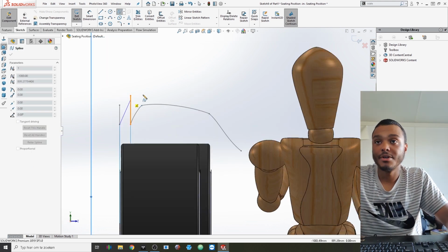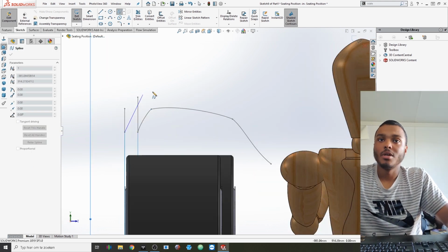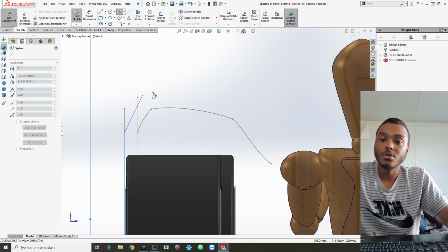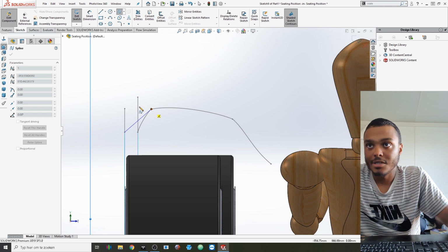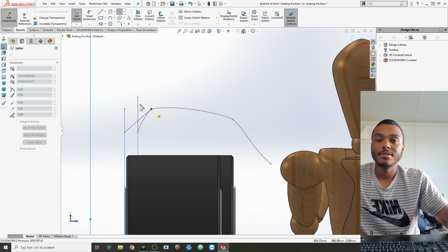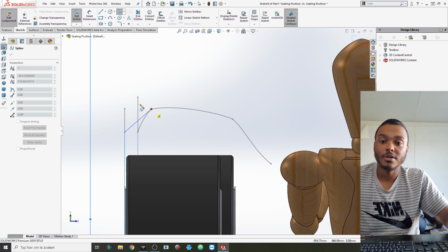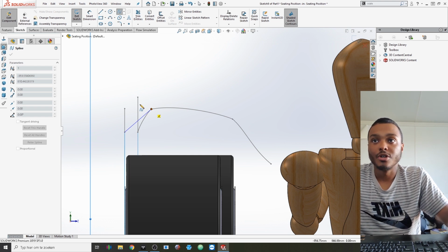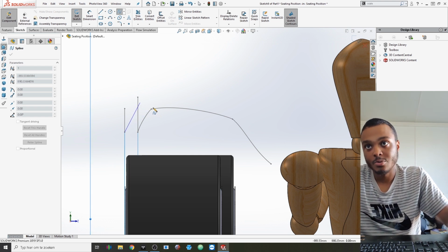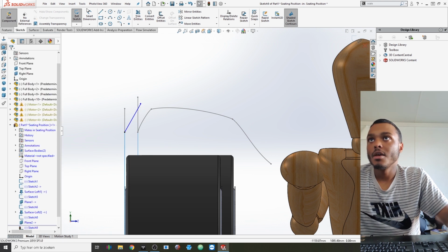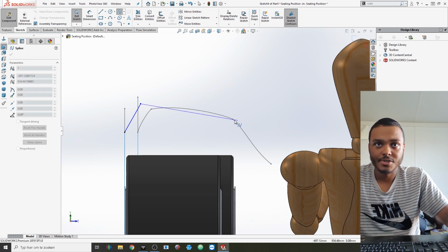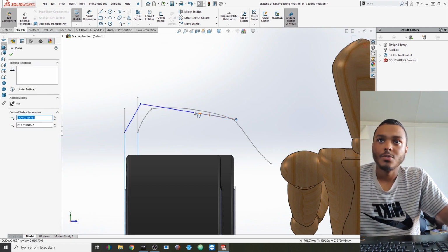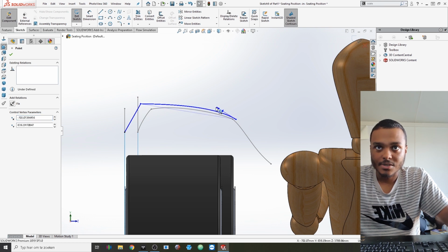And like I said, we're now at the back portion, so we make the rear look a little bit stronger, a little bit bigger. So we can see this line obviously, and we're just going to use it as a guideline to keep our dimensions and everything straight. So we're going to make it a little bit higher. From this point you can see that I'm taking it a little bit up, and then from this point I'm going to take it a little bit wider, so it's not the same height, but with the guide curve you can see that it's always staying there.